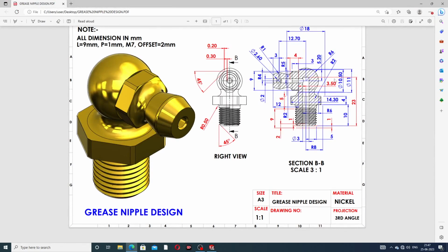At first, draw some geometry, click here. This body design: at first the radius is 6 mm, the curve is 2 mm. This distance is 4 mm, and this distance is 10 mm. This center distance is 5 mm, and this full distance is 8 mm radius and distance, and this middle is 6 mm.